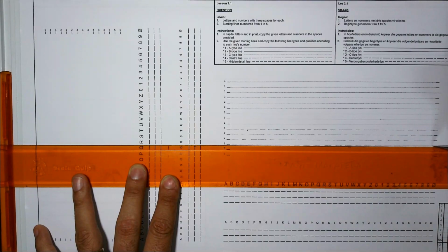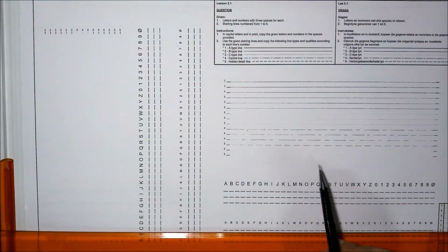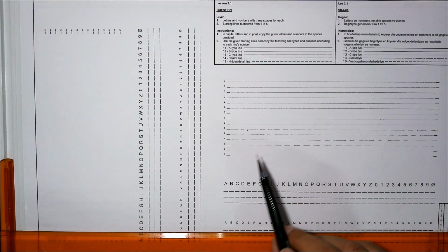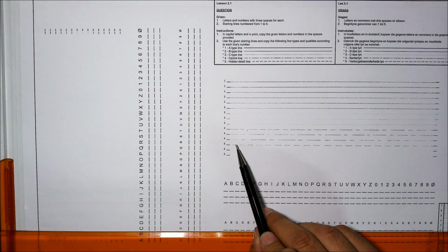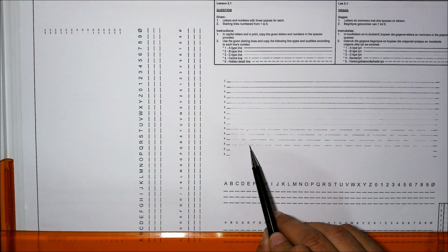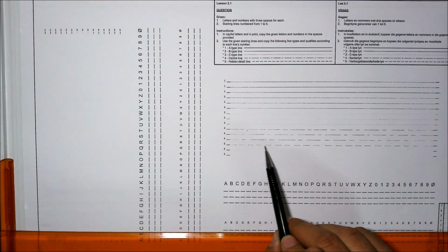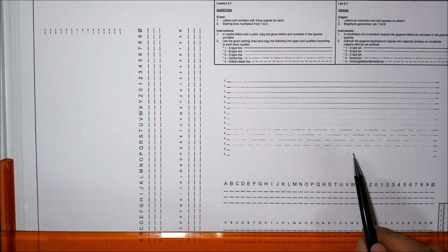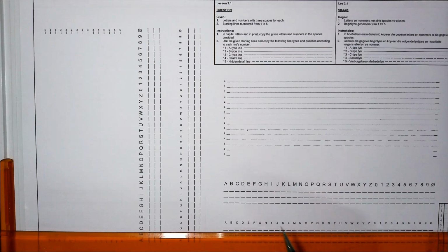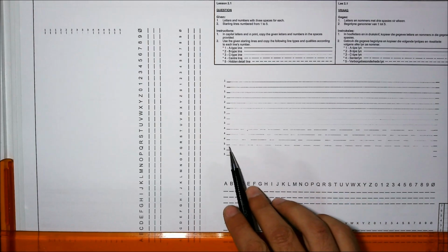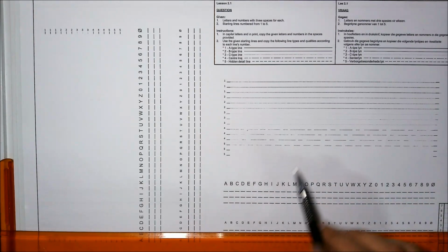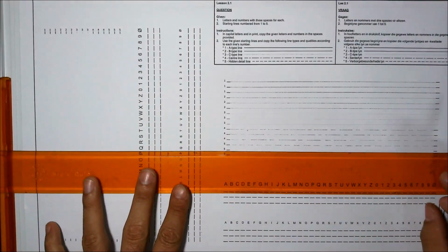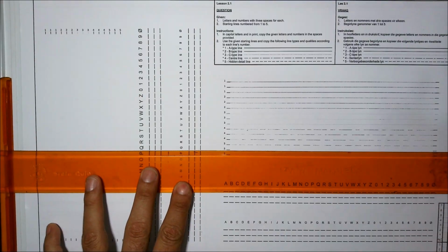And in your sequencing, try and do this. Keep the lines as close. You can see I'm kind of deviating here on the side a bit. That's why I'm saying this. You have to try and keep the spaces in between the dashes the same. You have to keep the line roughly the same as well. You can see I've started quite short and I ended with a longer line. Now, typically you're not going to draw a hidden detail that's this long. So it might be very short segments, which makes it easier to digest at the end of the day and to draw.